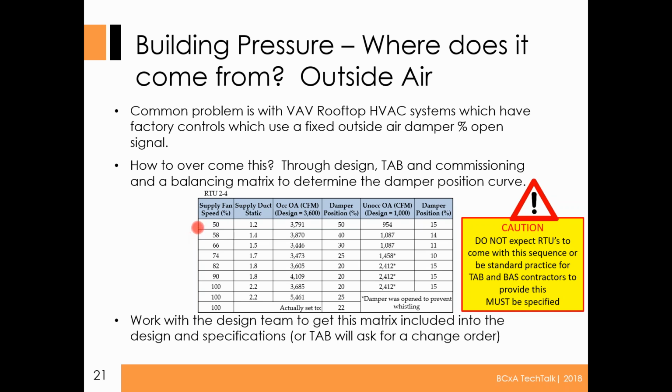This is one where they actually specified the 1, 2, 3, 4, 5, 6, 7. This was a 7-point plot. It was actually specified to plot out the 7 points. So we were using the VAV boxes, the real system. It was not just overriding the supply fan to do this. So we were getting pretty realistic data of how the system will perform. And that's a great question.